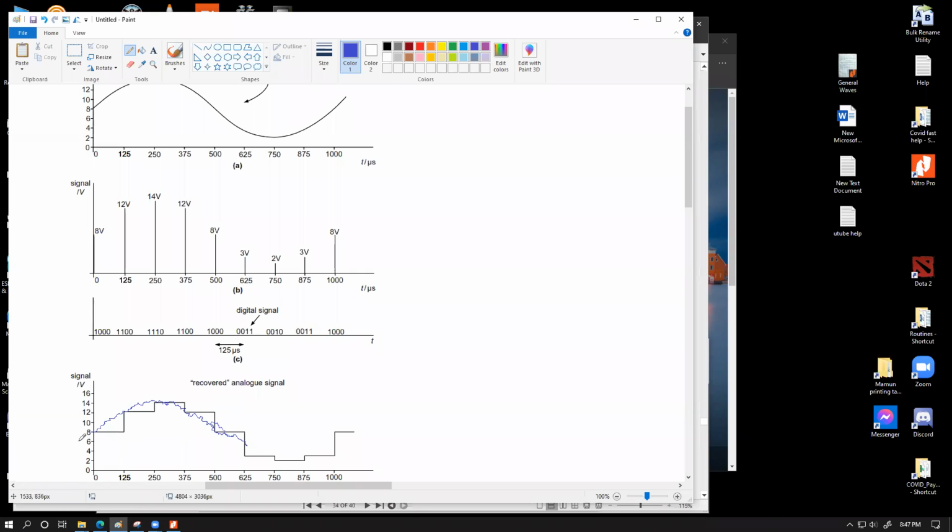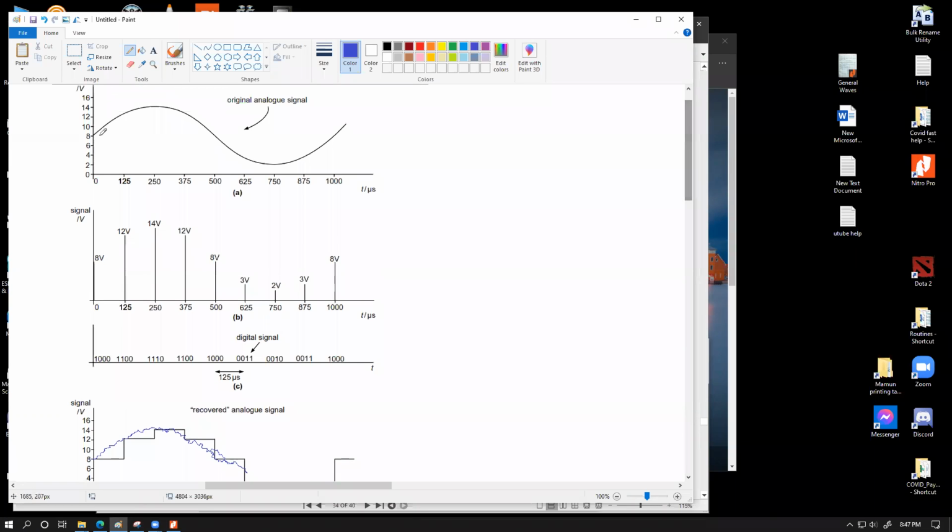so what I'm going to show you is, here's the deal. In this case, we made the observation after every 125 microseconds. This was happening for an 8 kilohertz sampling frequency. What if we had a 16 kilohertz sampling frequency? Or maybe a 20 kilohertz sampling frequency. If our sampling frequency was much bigger, then there would be more incidences of observation within this part, which means other than producing 8 and 12 volts within a gap of 125 microseconds, you'd be getting another set of data over here, maybe another set of data over here.